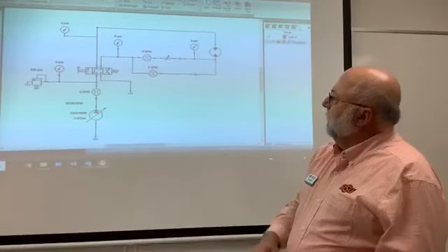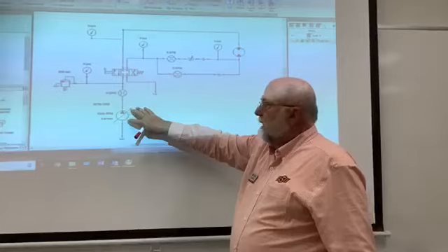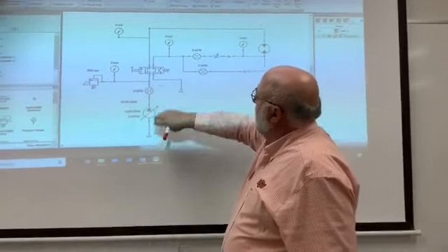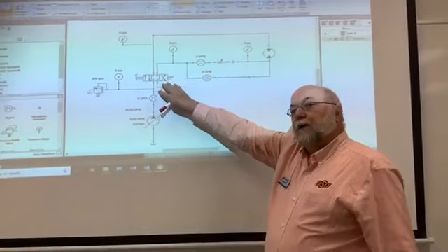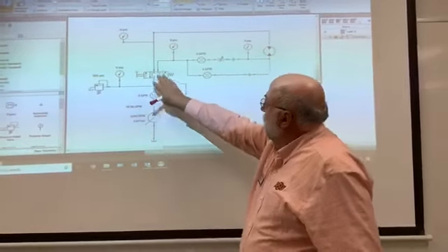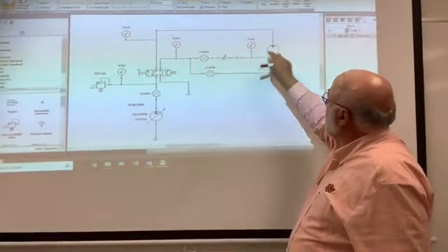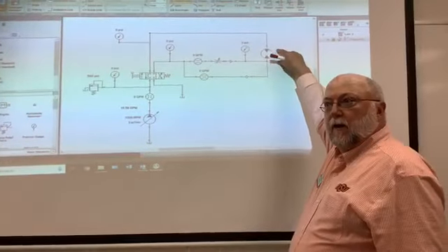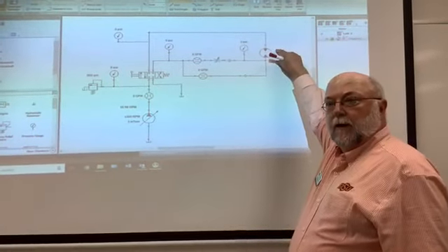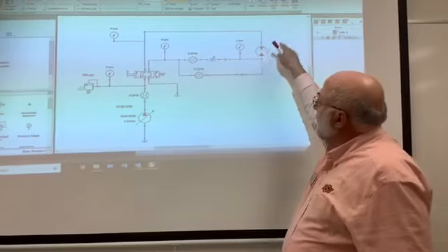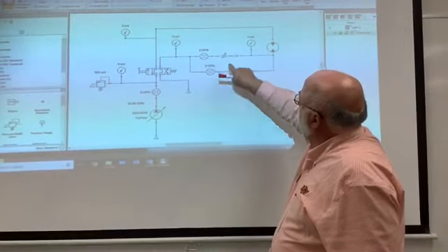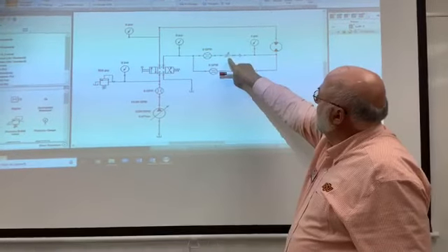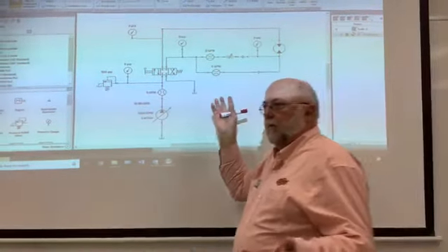simulate. I've got a pump here that's driving hydraulic fluid. Here I'm measuring the flow. I've got a pressure relief valve over here. I have a directional control valve here, which will control the direction of this hydraulic motor out here. It'll spin in one direction or the other. And then we've got some flow meters in here too, and this little symbol here, a flow control valve.